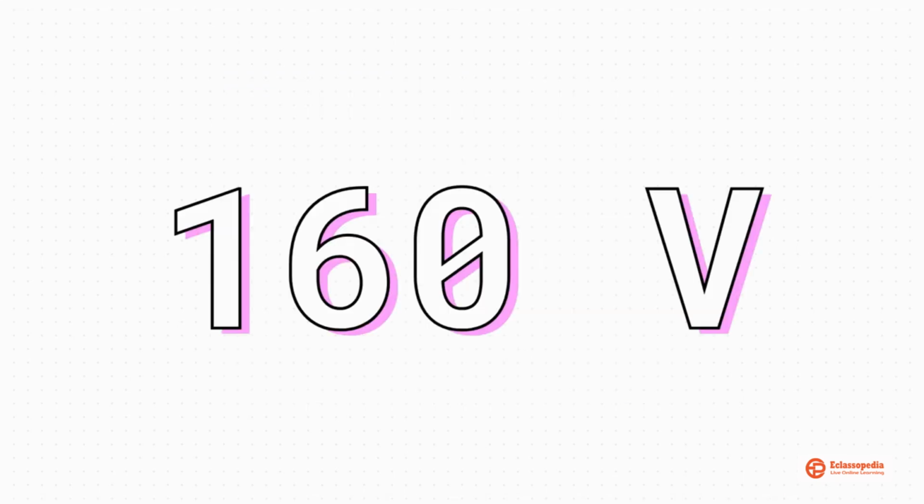Let's put this into perspective with a quick real-world example. Picture an everyday electric iron. You know the resistance of the iron's heating element is exactly 50 ohms, and it draws a current of 3.2 amps. So how much voltage is required to actually make this iron work? Using our formula, voltage equals current times resistance, we just multiply 3.2 amps by 50 ohms. And that gives us exactly 160 volts. That is the precise electrical pressure needed to push that specific current through that specific iron.